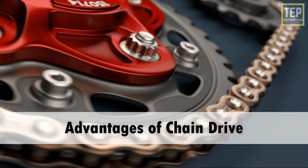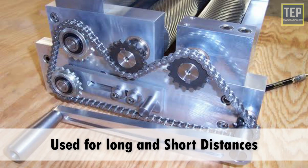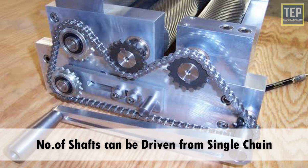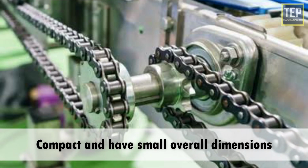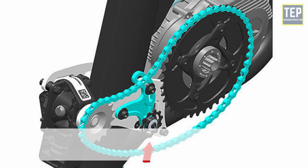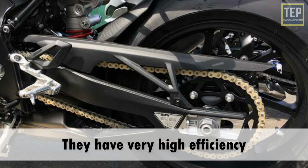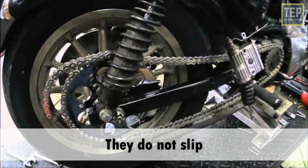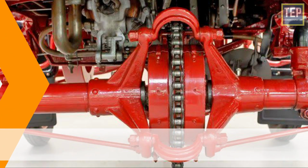Advantages of chain drive. They can be used for both long and short distances. A number of shafts can be driven from a single chain. They are compact and have small overall dimensions. They do not present a fire hazard. They do not require initial tension. They have very high efficiency. They do not slip and are easier to install. They can withstand abrasive conditions and can operate in wet conditions.